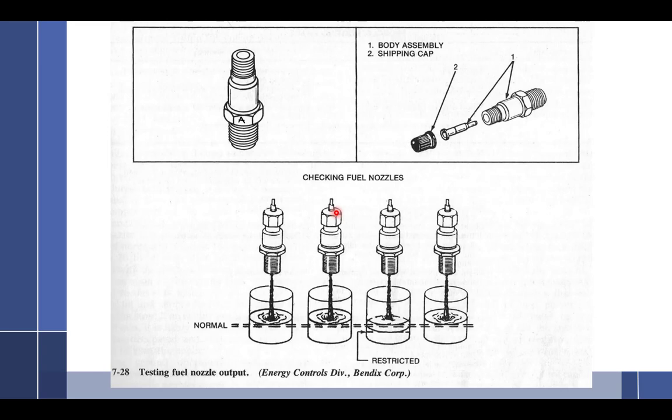So we go there to troubleshoot the engine and took off the flow divider, and it's packed full of rubber. Just all this rubber shaving. There's a screen in there, just packed full of it. And so, we cleaned it all out and said, what we need to do is disassemble all of this, flush the whole system. And he was on his way to somewhere, and he refused that service.